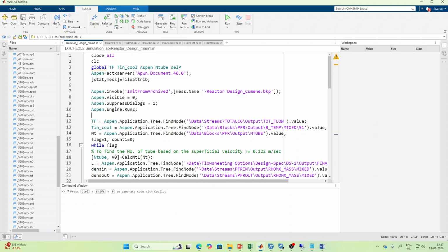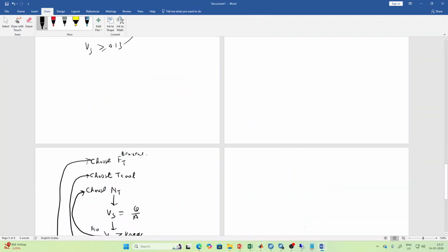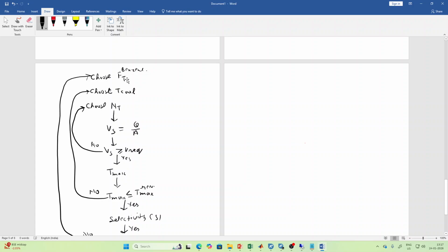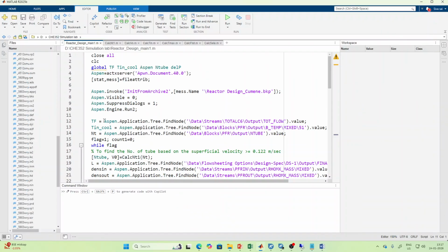Okay. Now you have three variables. All other variables you have calculated using the Antoine equations or your other equations. So only three variables are here, and for these three variables, the loop looks like this. The outer loop is total benzene, then the inner loop is T equivalent and T. In the same way, I have defined this variable. Let's say the variable name is total flow, that is TF. We want the initial value of TF, which I have taken from Aspen Plus itself, whatever value we converged to initially.